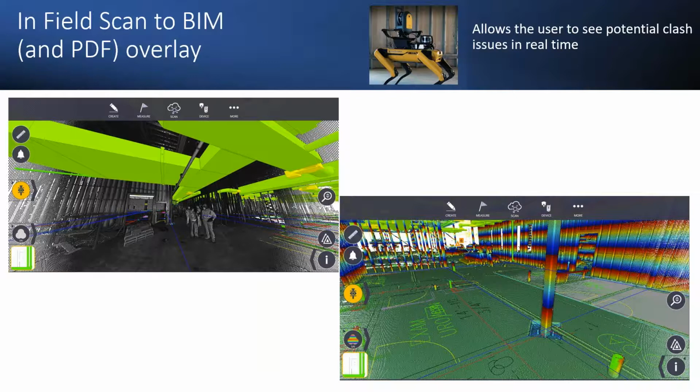and now we can see, with detailed measurements, in this case, this was a hospital, where the exam rooms are going to be, where the doors are going to hit, any type of stub up. So you'll see on the lower right-hand side here, you'll see a stub up that's in place, and make sure that that's within the walls for any type of drainage for sewer or septic. Upper left-hand corner, we've got scans, and we actually have a 3D model that we've scanned against. So now we can look for visual clashes.